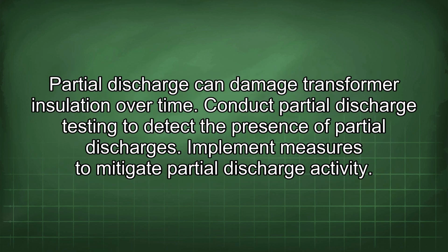Partial discharge can damage transformer insulation over time. Conduct partial discharge testing to detect the presence of partial discharges. Implement measures to mitigate partial discharge activity.